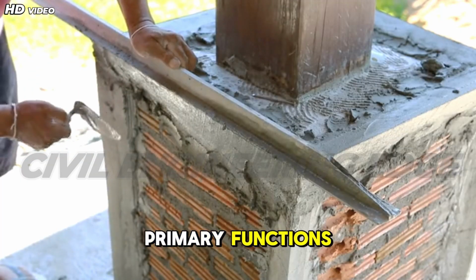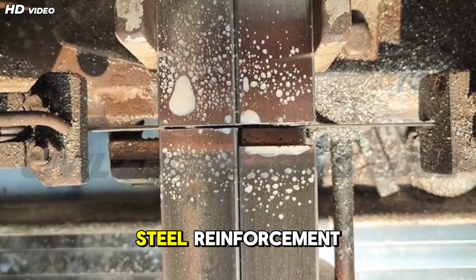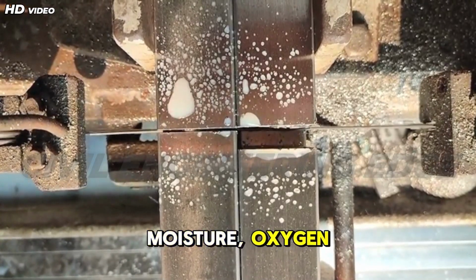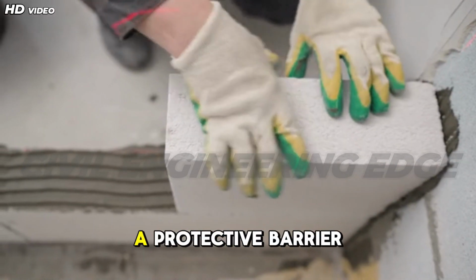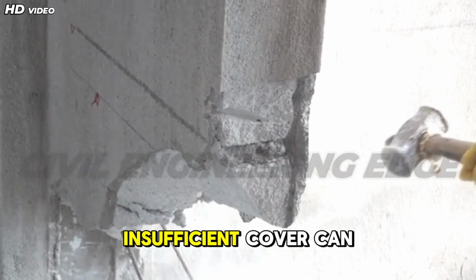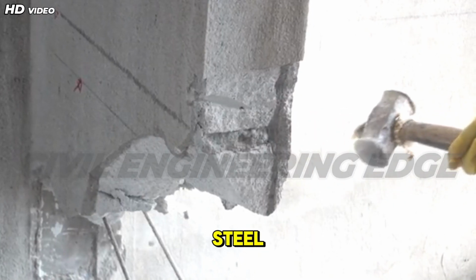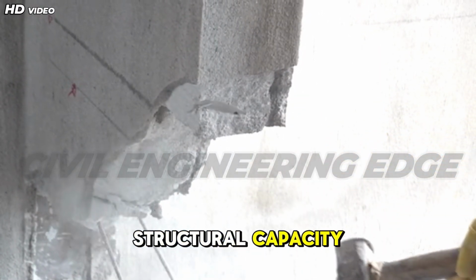One of the primary functions of concrete cover is corrosion protection. Steel reinforcement is susceptible to corrosion when exposed to moisture, oxygen, and aggressive chemicals. Concrete acts as a protective barrier, preventing these agents from reaching the steel. Insufficient cover can lead to early corrosion, causing expansion of steel, cracking of concrete, and reduction in structural capacity.